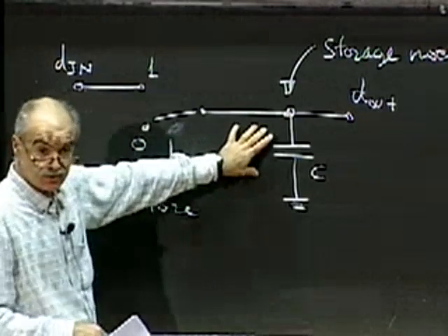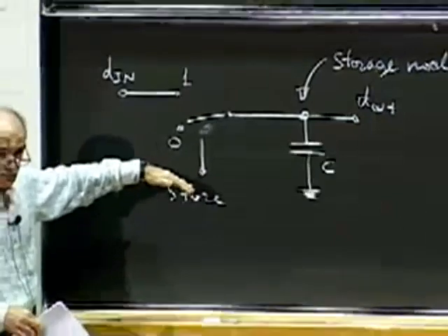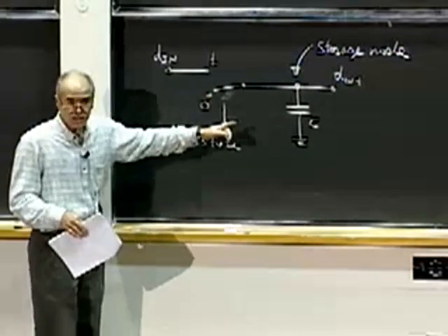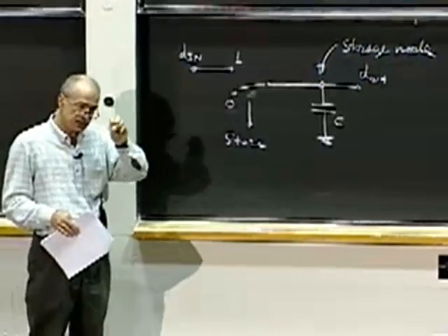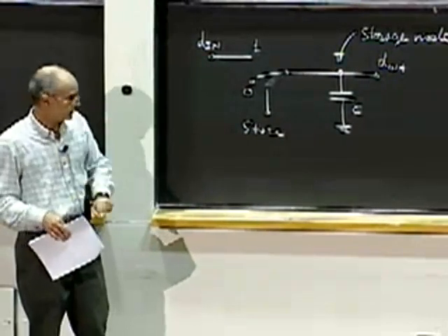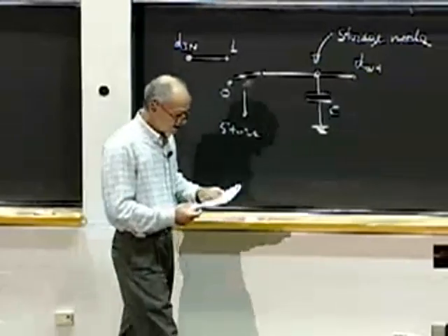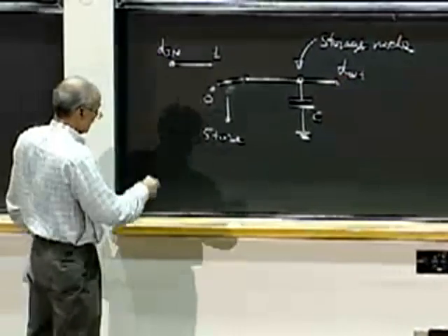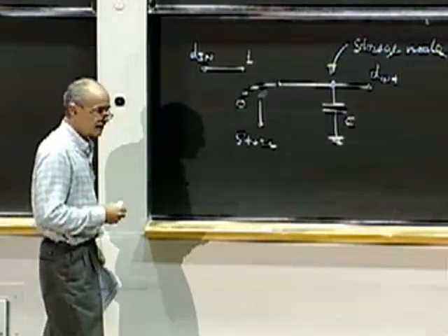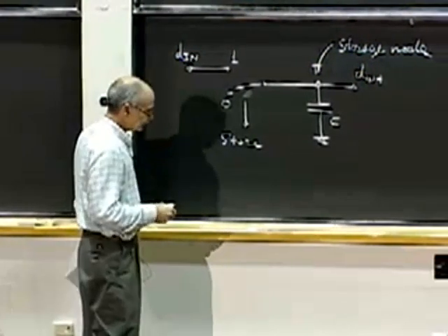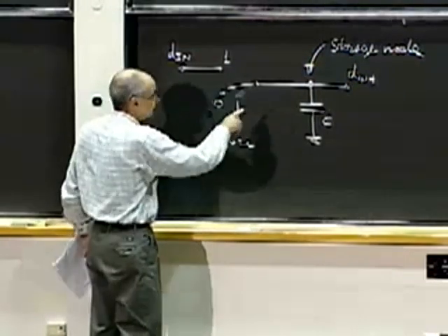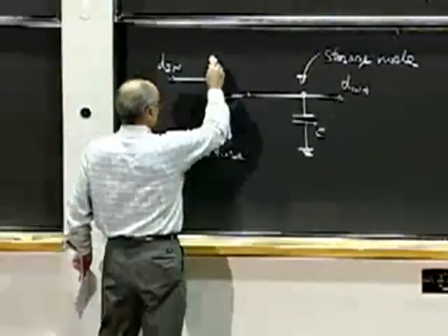Okay, so it does store the value of the voltage that it saw, 5 or 0, high and low, okay? It stores it because it stores charge, okay? So that's actually the physical quantity that is stored. It's manifested as a voltage, which we see, okay? All right, before I move from here, so what is the basic cell in a DRAM? You know, one that you go out and buy by the billions of cells. It's actually this. The only difference is that this switch here is replaced with a MOSFET.